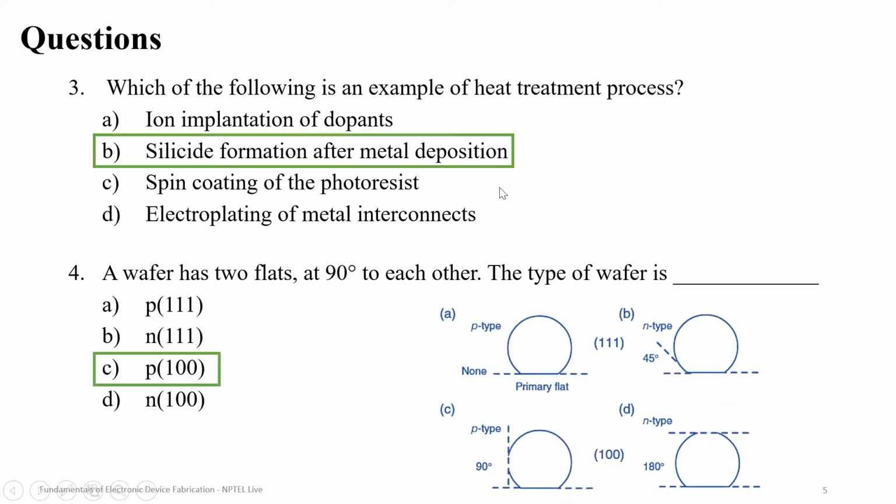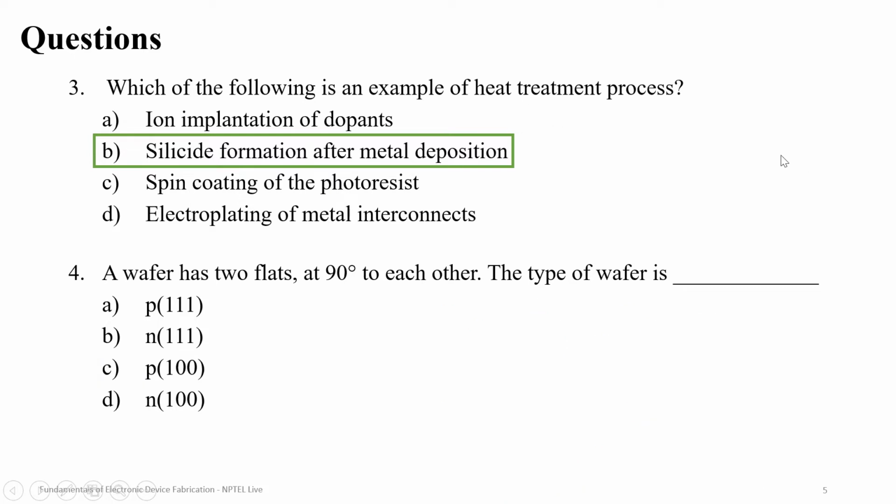In wafer fabrication, there will be different processes, right? So first one is layering. We will have a P-type or N-type wafer, and we will be depositing an oxide layer on top of it. That is the layering process. After this, we will do patterning. We will use photoresist, which will create regions that are active to light, and using that, we will be able to create specific patterns on the wafer. And once that has been done, we can dope the wafer from the beginning, or we can do doping later on also by layering.